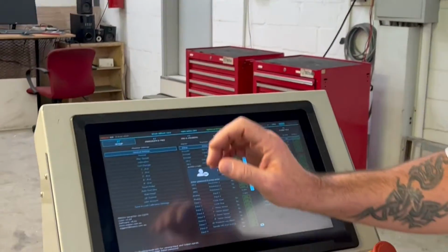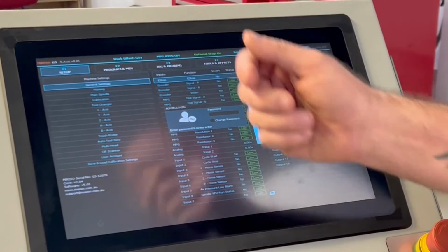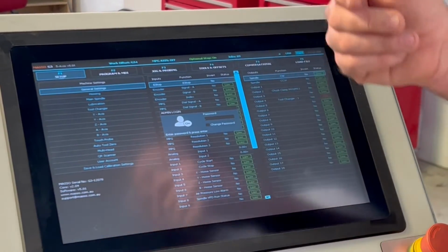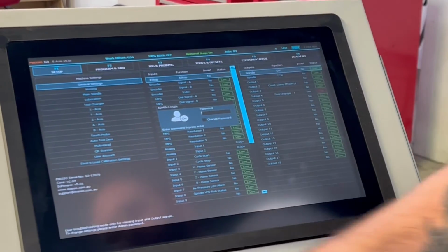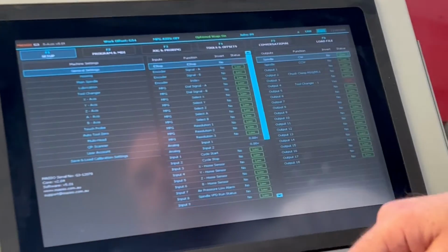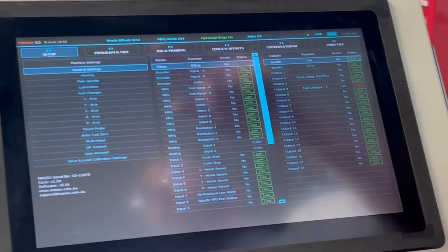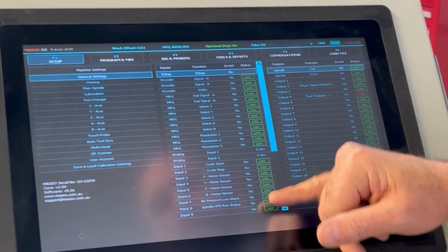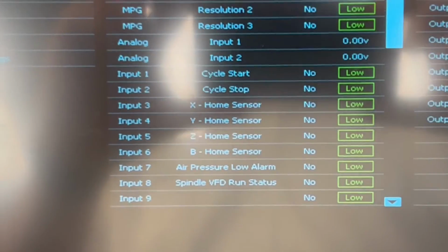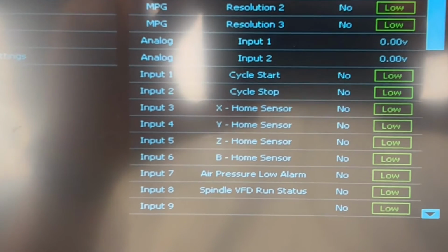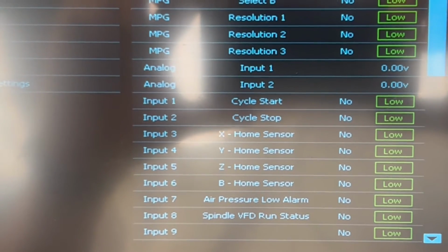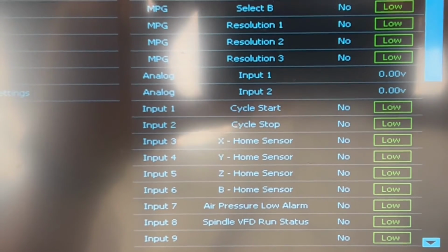This page will be used for testing inputs because LEDs will light up, and that'll be a completely different section on maintenance or troubleshooting. But to show you quickly, if I press enter, the box disappears. If we press one of the homing switches, which will be explained to you, one of these LEDs will light up. Okay, X home. There we see it busy changing. Z home, busy changing. Right. Y home, fantastic.